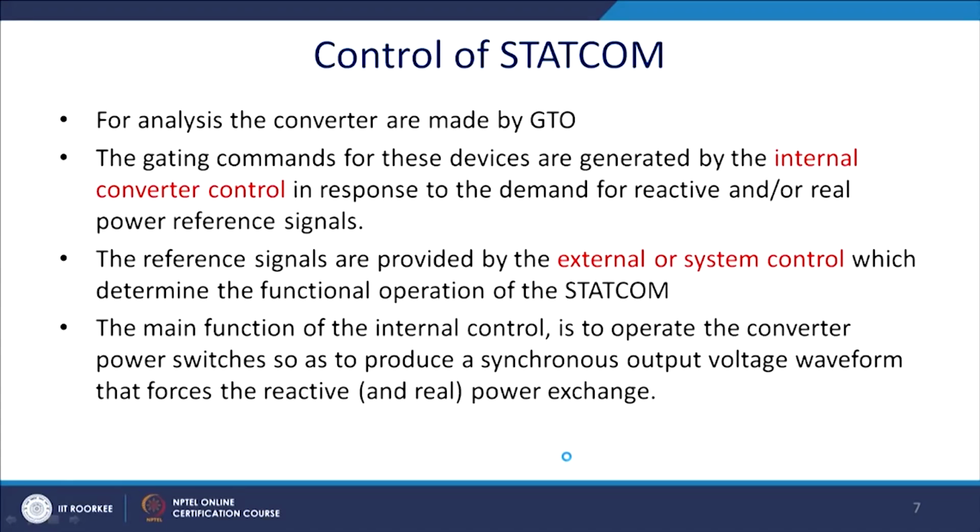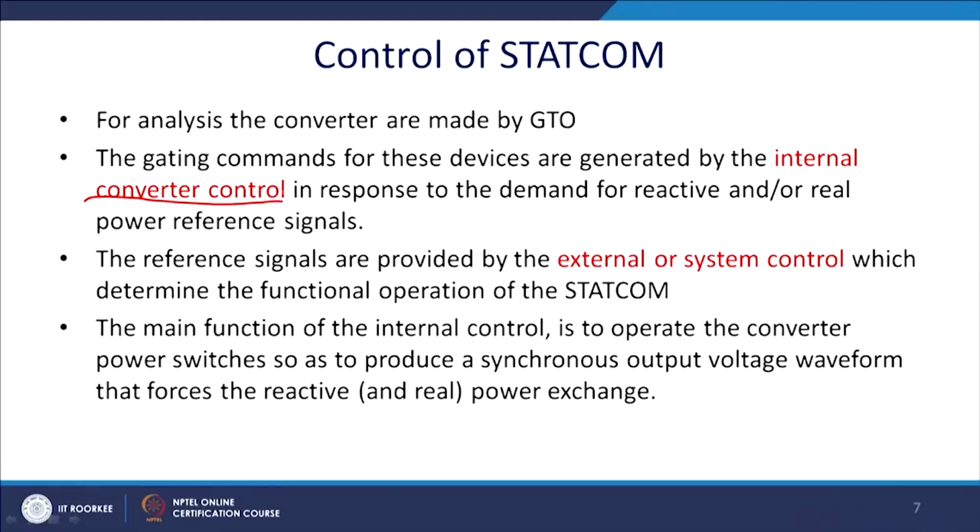For analysis of the controller, we consider that these devices are made of GTO because they require fully controlled devices, and maybe for the lower rating we can use IGBT. The gating command of these devices is generated by the internal converter control in response to the demand of the reactive or the real power generation.